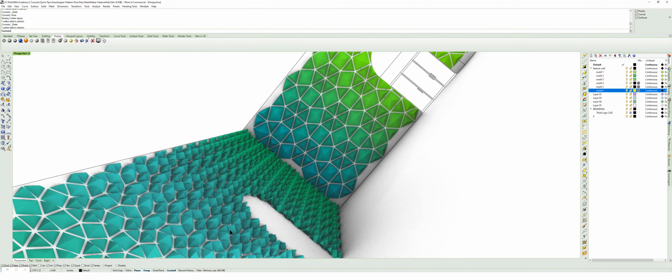Taking my surface output and my surface input, that is the first step. Now the next step is we need U and V, UV coordinates. And to get that, we're going to go up here, do surface closest point, plug that same surface in. And now the point we need to evaluate it against is something that's specific to my polyline curve. So what I typically do is type in area, which is going to give me not only the area, but the centroid. So plugging that curve in, it's going to give me the centroid here.